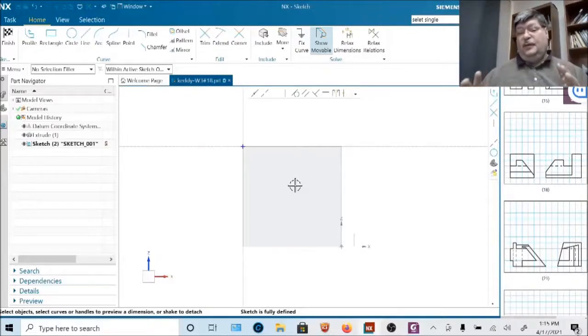Okay, so we're in the front view now, looking at this part, and I want to draw this shape with this diagonal line on it, this perimeter. And then we'll have to cut this inclined plane off later. So the simplest form of modeling is to create a sketch and then extrude it. I say that the simplest is it's like the first generation, if you will. It is easier to edit the solid later with other commands like chamfering off or making an edge blend or curve on a corner rather than doing a sketch and passing it through it.